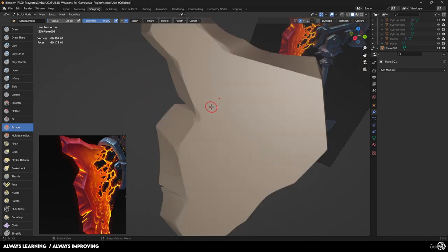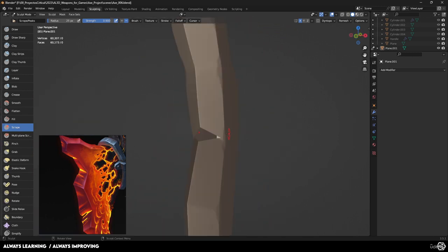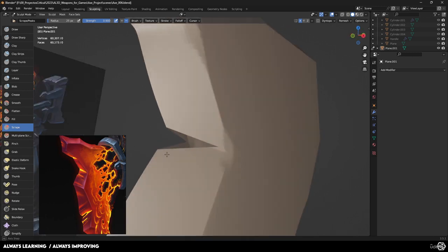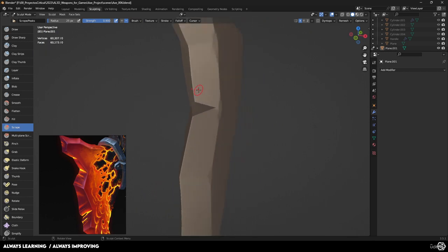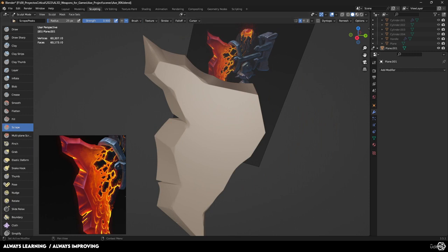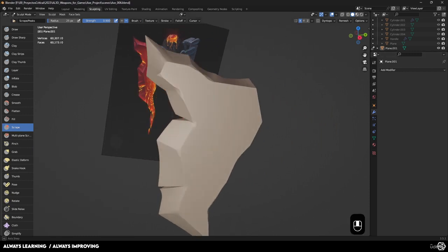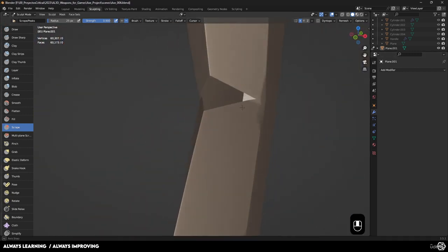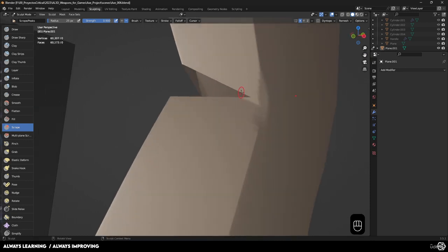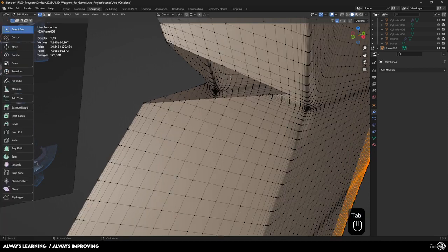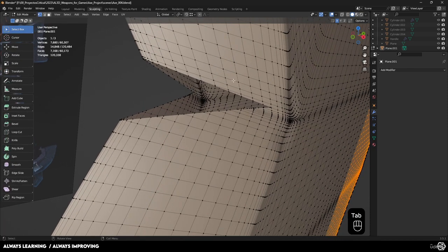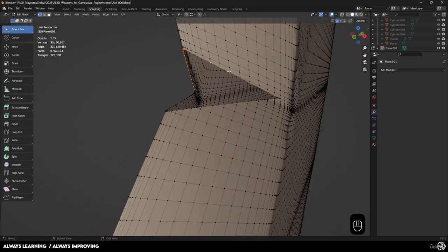Oh, okay, so the reason why this is not working is, again, because this thing right here does not like booleans. It's non-manifold geometry because it has an empty element. So here's how we're going to fix this. The way we're going to solve this is actually rather simple. The only thing that Blender needs to do a proper remeshing is to understand that this is a solid object.